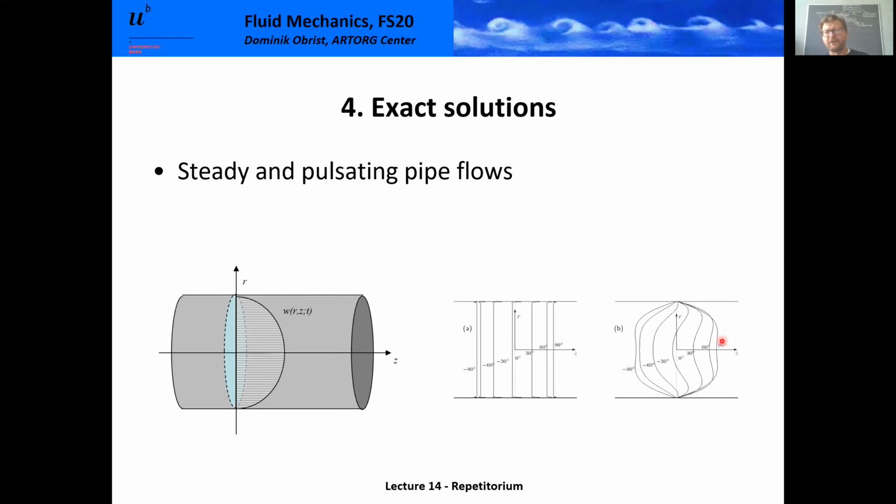And then we made a very important generalization. We said, well, this classical Poiseuille flow that everyone is talking about is a steady flow. But especially in the body, you as biomedical engineers will have to deal with pulsatile flows that are changing in time. Not just the heart is pulsating, many other things are pulsating.